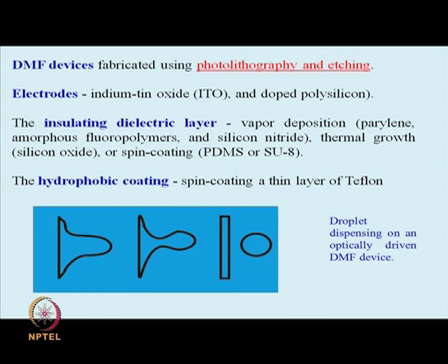This is something which I have not covered. So far we have seen that by applying an electric field, you would be able to change the surface energy, and when you change the surface energy, the manifestation of that is in a change of the contact angle. If the contact angle changes in a non-uniform, asymmetric way, then the droplet will move to a certain side.